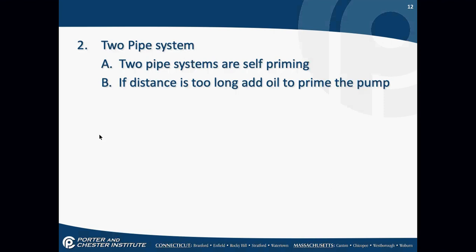So while we're bleeding the air out of the system, we have to bypass the safety, basically. We have to pretend there's flame when there's no flame there. So how am I going to do that? Here's my primary control.